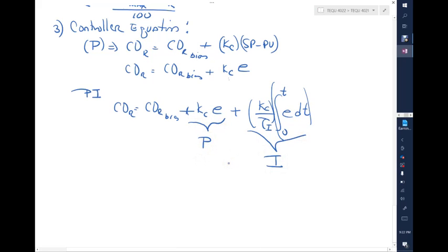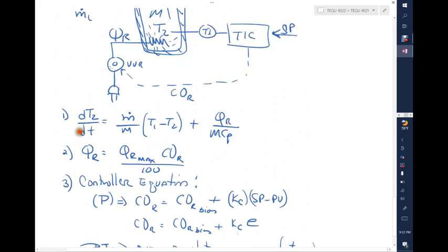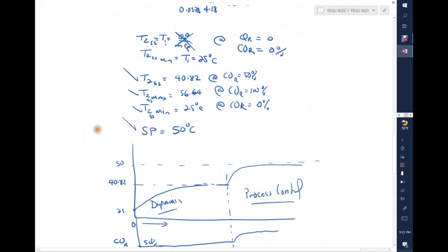And this type of controller, this PI controller, is better for systems that auto regulate, systems that behave nicely, in other words. So you have a good steady state value like shown here. A system that will do that is nice, you can use a PI controller and it will work wonderful on it.